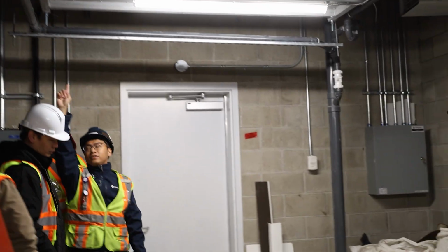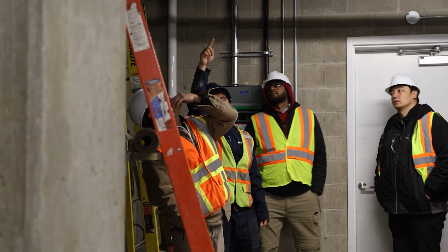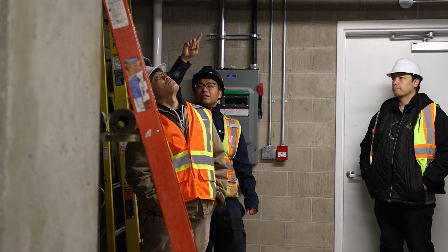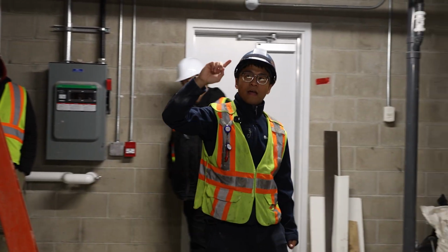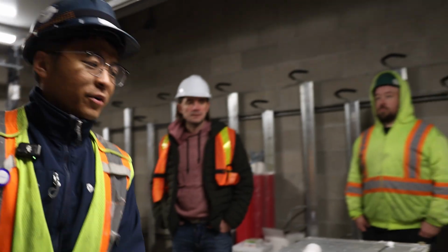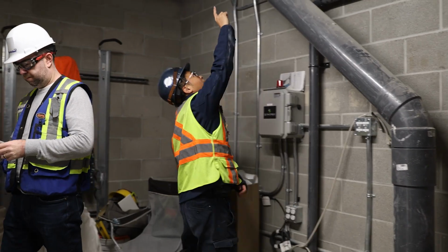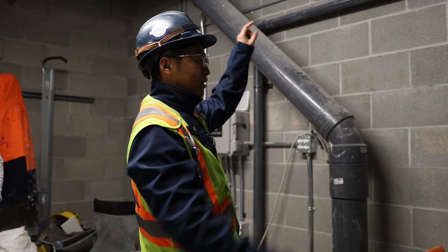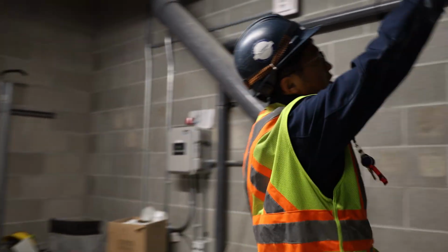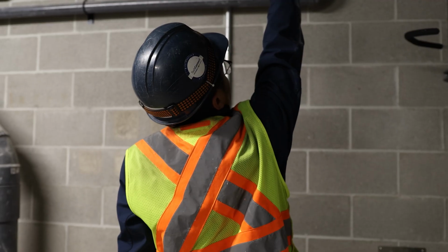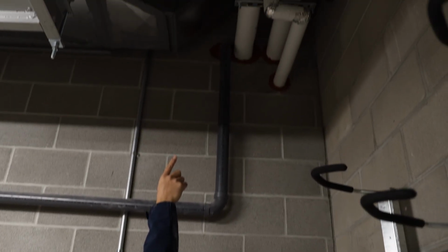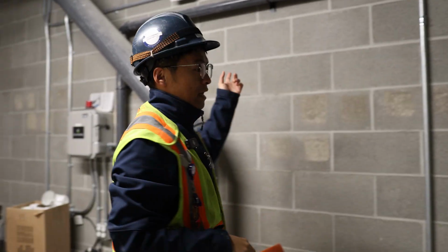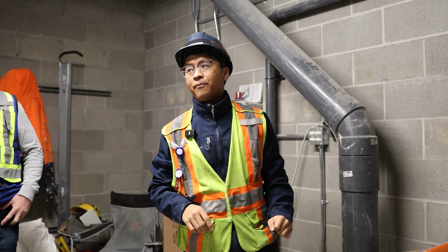And then there's a filter pressure sensor that tells you the filter status, when is the time to replace the filter. And then we have our supply temperature sensor and the supply pressure sensor over here, just above this ductwork. And at the discharge, it splits to two ductworks. That's one of the discharges. And we have a supply actuator over there. And then the other one goes the other side. And we also have another supply damper with actuator.